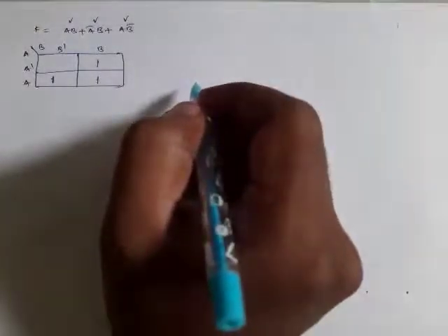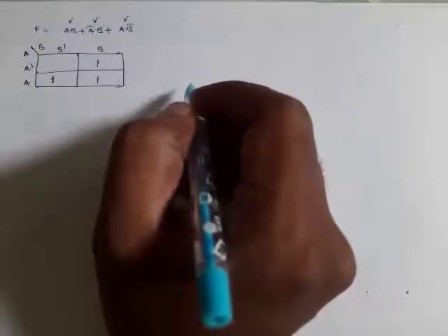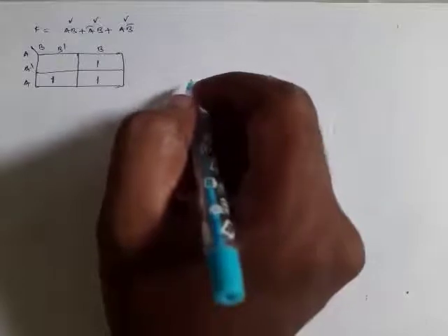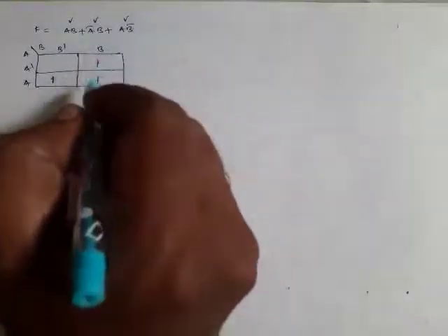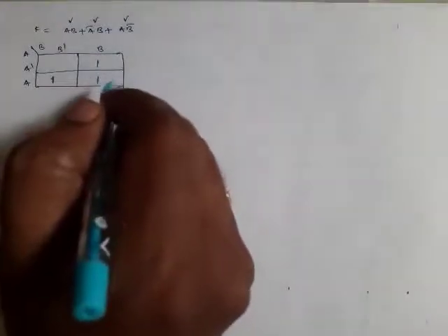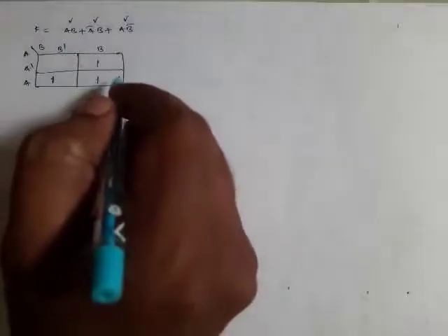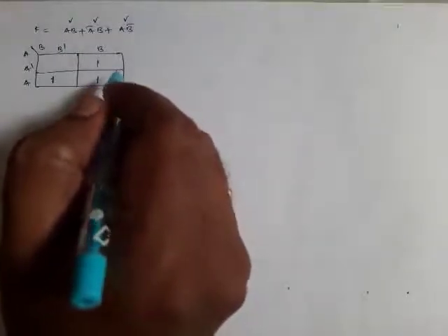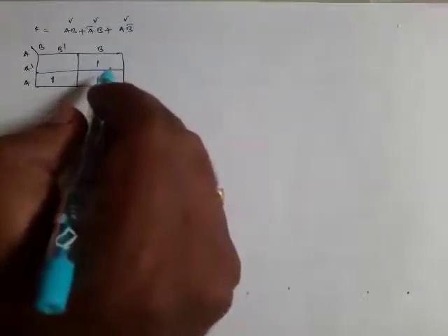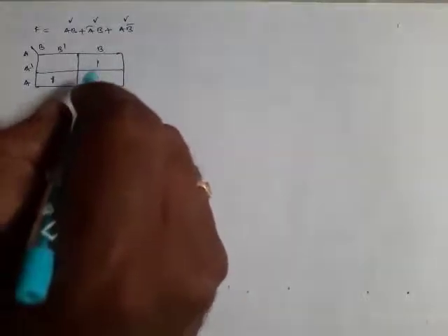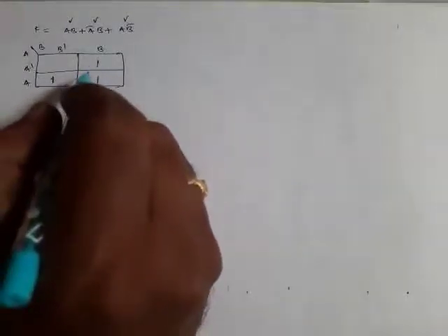And here we'll see how the properties of K-map can be used for simplification of the function. When I represent the function in this way, here you can see that we have represented the minterms of the function by entering 1 into the corresponding cells.